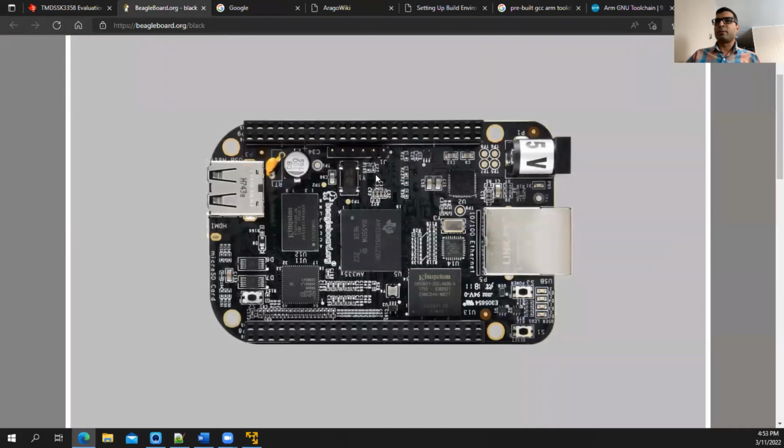So this is the well-known BeagleBone Black board. The same chip is on here, but the BeagleBone Black has the HDMI output and eMMC, and obviously 512 megabytes of DDR3 RAM. But in our case, I'm just trying to use the LCD, which is more common in the industrial format. So I selected that board, but obviously we can run the HDMI output as well.